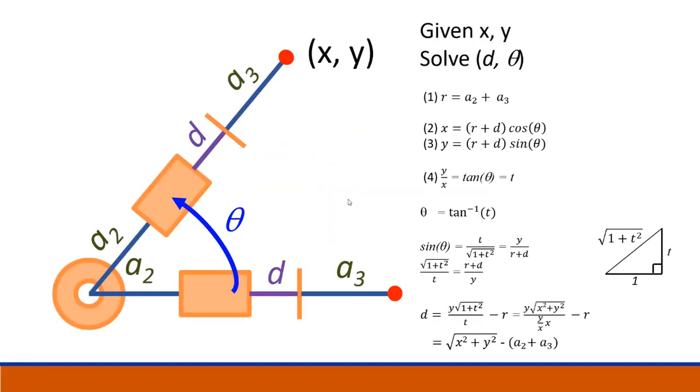So now look at the top view. In the top view, you will have only XY. Okay, so you do know about your XYZ, we don't care. And then now you use whatever XY is given, you want to solve your theta. Theta is the amount you will rotate, and the extender D. Okay, these are the numbers you want to have. So basically, you know about your XY, you want to solve this D extender length, and this is theta.